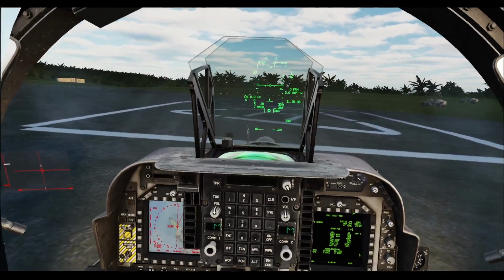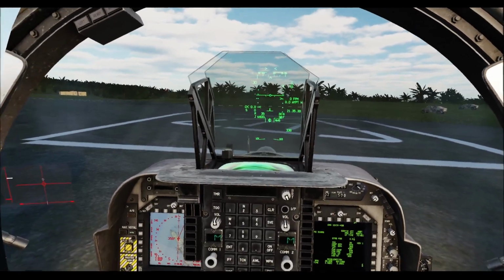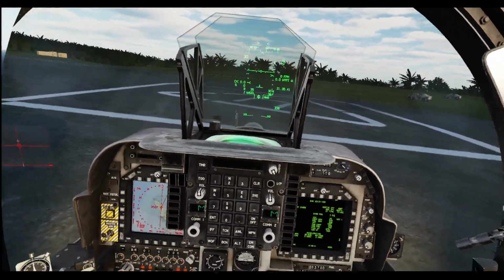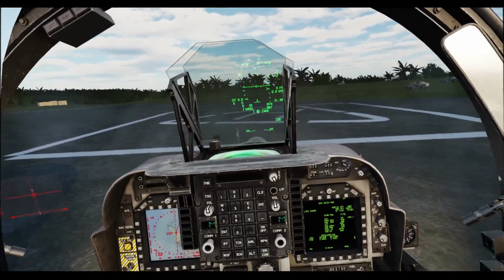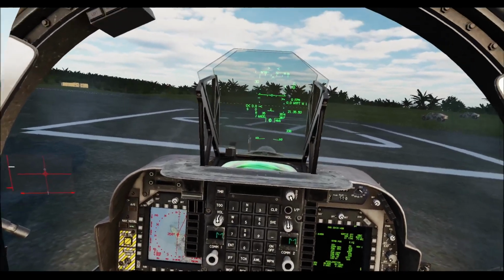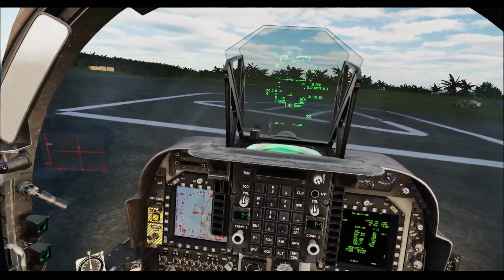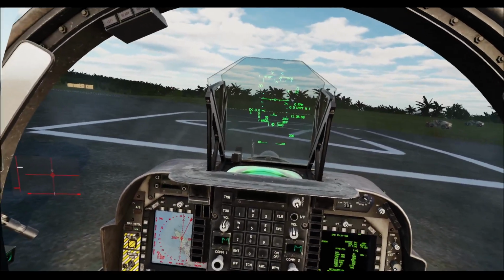I'm going to level out at 1,000 feet. I'm going to trim on AOA for 10 to 12 units of AOA straight and level. I'm then going to perform the turn. During the turn, I'm going to look to be 0.3 to 0.4 miles on the delta distance halfway through the turn, and I'm going to look to roll out parallel to the runway at between 0.8 and 1.0 nautical miles.